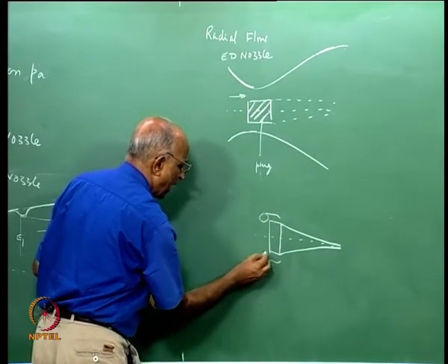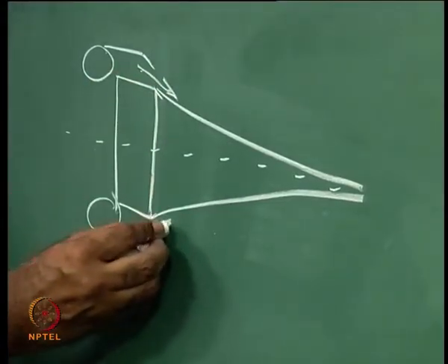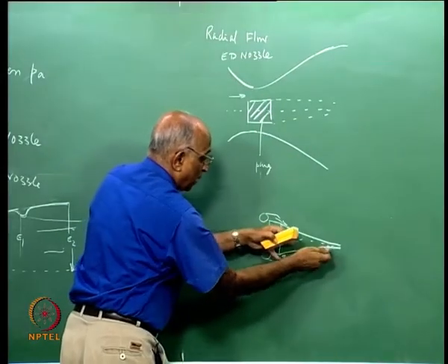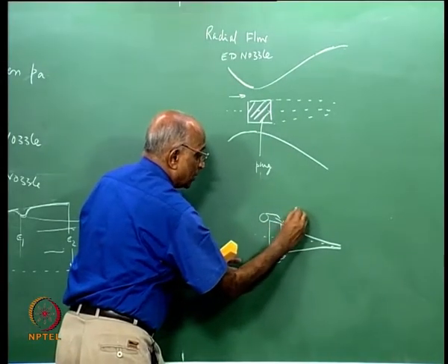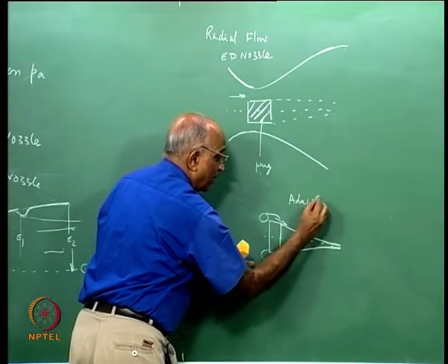In other words, I have an annular chamber over here, I allow the flow to come across this, I allow the inner contour instead of the outer contour to balance the flow, keep the outer open such that it is again a case of an adapted nozzle, it can adapt to any condition.